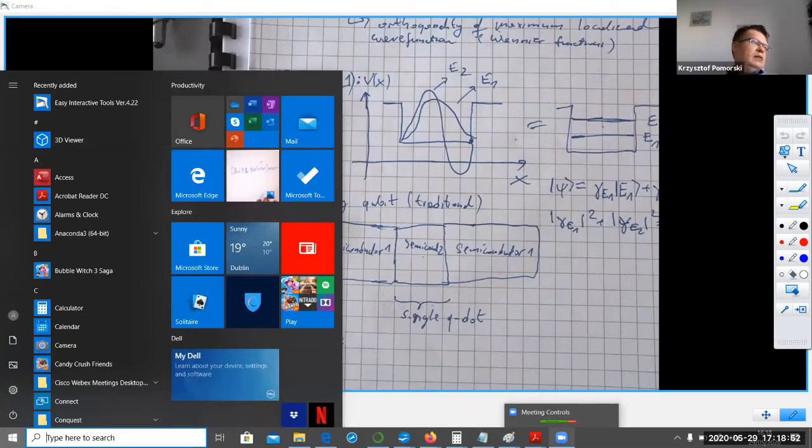So if there is a potential difference of half a volt between gates, and it acts at a distance of 30 angstroms, there is a very big gradient of electric field that is able to accelerate the electrons or holes, so some of them can become carriers when they are bound to atoms.